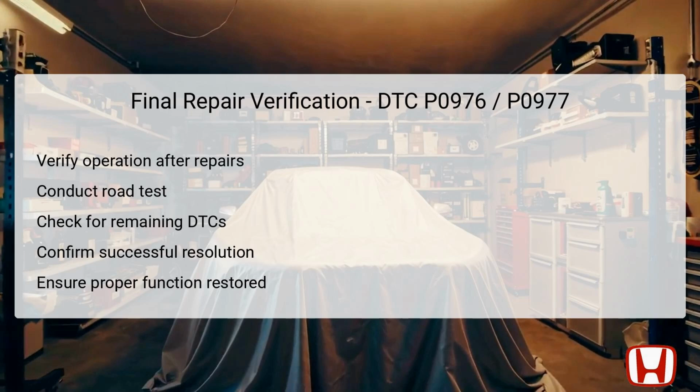This involves performing a thorough road test to confirm that the transmission operates without any shifting issues or warning lights. During the road test, observe the vehicle's behavior to ensure that the previous symptoms do not resurface. Following the drive, utilize the diagnostic tool to scan for any lingering DTCs that may indicate unresolved issues.